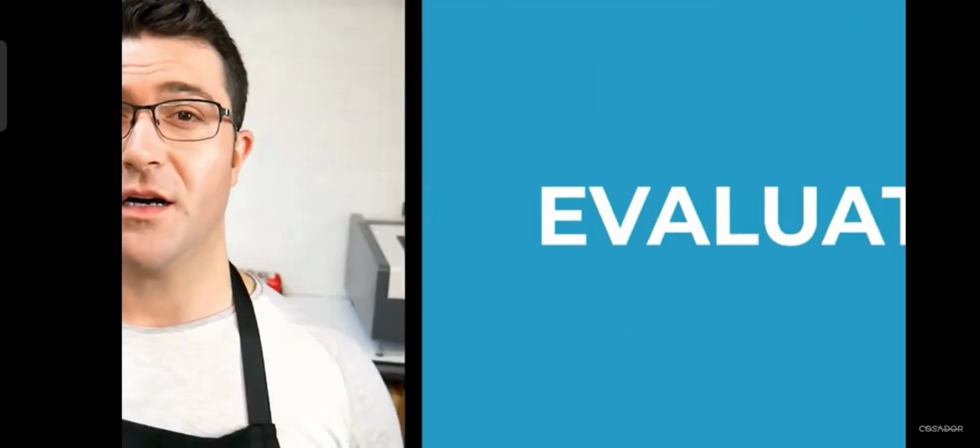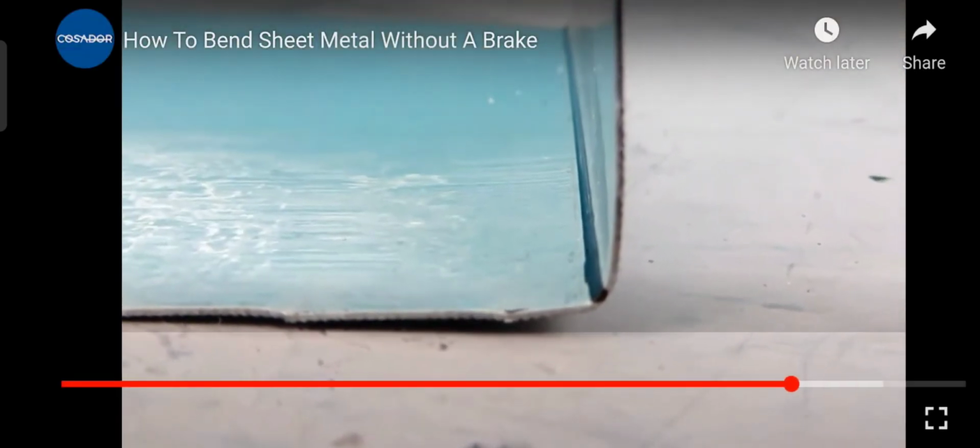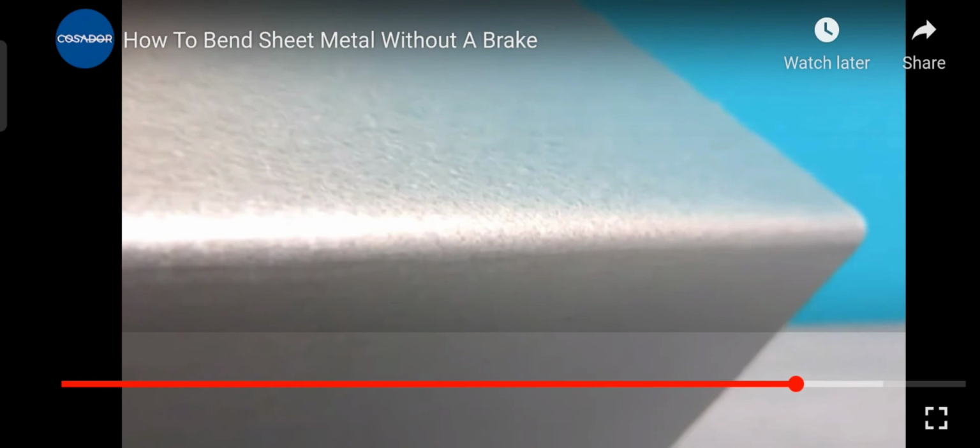Okay, evaluation time. Personally, I think each of these methods have a purpose. I would bend by hand if that were my only choice and a sharp radius isn't absolutely necessary. I would use a hammer if I wanted a really tight bend, but I had time to refine the surface afterwards. I would score and bend if I wanted to control a long hand bend, but I didn't have a roller or the material was too thick, providing that I could protect the score mark from corrosion. And I would use a roller if I was working with thinner sheet that was going to be used externally.